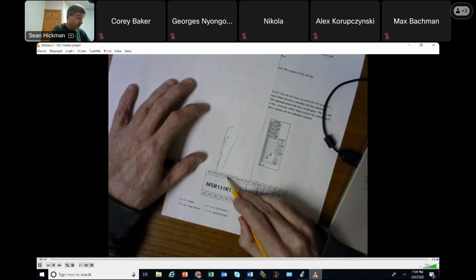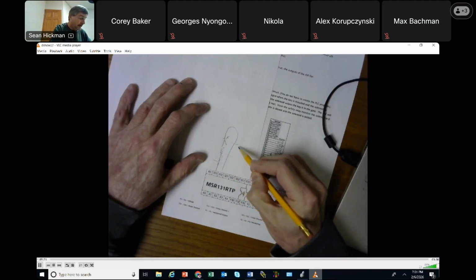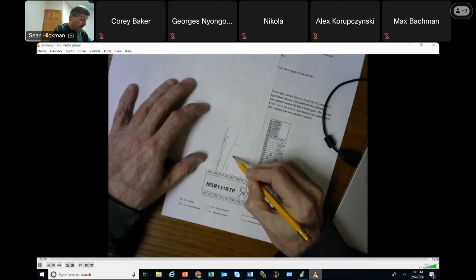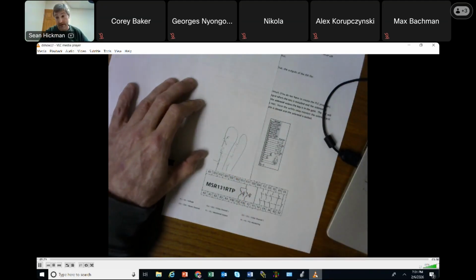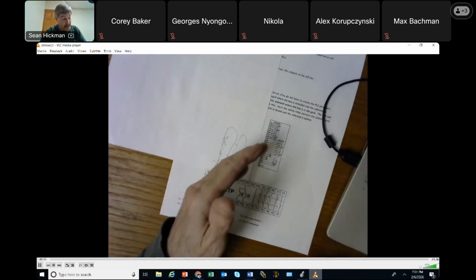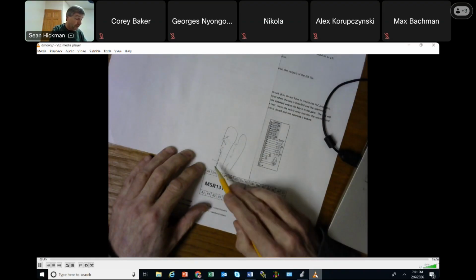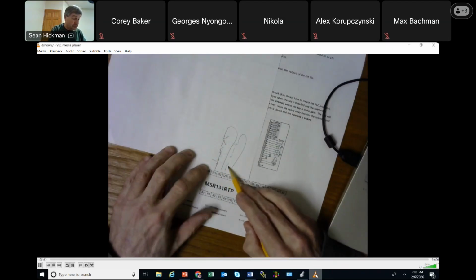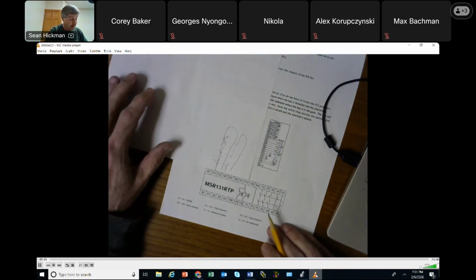And then this channel is going to have the same duplicate set of contacts running through here, back to there. So all these contacts just become redundant, and how you pass them through all these safety devices, there's a lot of options, okay? But I think everybody's feeling pretty good that you can pass multiple E-stops, two E-stops, another E-stop, safety relay, safety gates, whatever, okay?